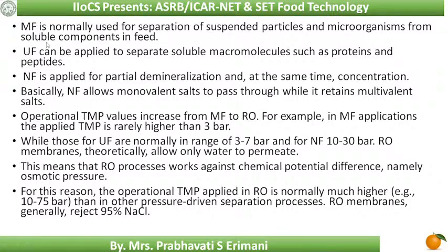Microfiltration for suspended particles and microorganisms, ultrafiltration for soluble macromolecules such as proteins and peptides, nanofiltration for demineralization and at the same time concentration also. Nanofiltration also allows the monovalent salts, and operational transmembrane pressure values will increase from microfiltration to reverse osmosis.